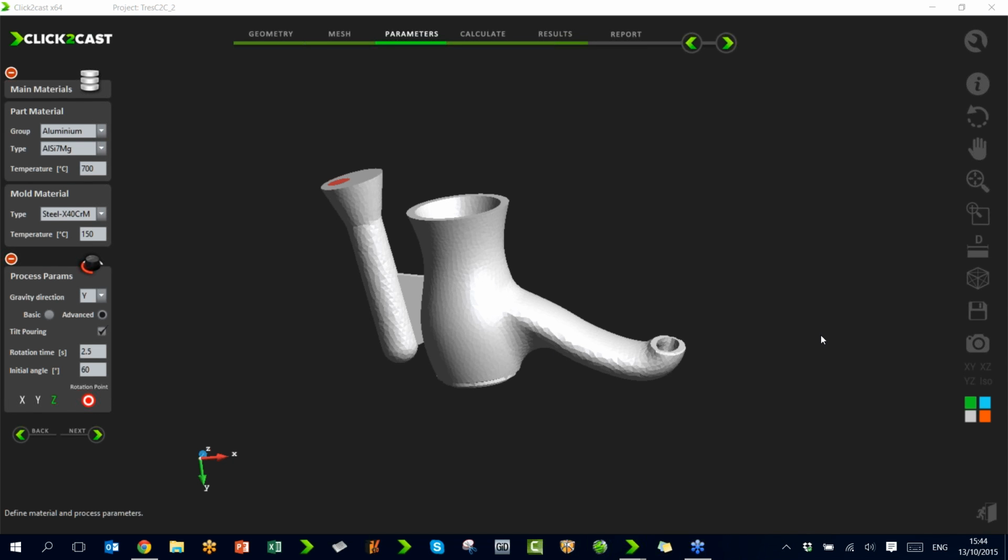Regarding the format for importing geometry, for the moment we are using STL files. We are using STL files because in this way we can perform automatic repair of the geometry. Our meshing tool is able to clean the STL files automatically. We can close holes and remove any element that is not useful for the geometry. We can do many operations to prepare and repair the geometry automatically, so we are using only STL files.